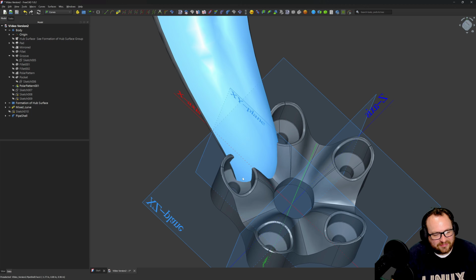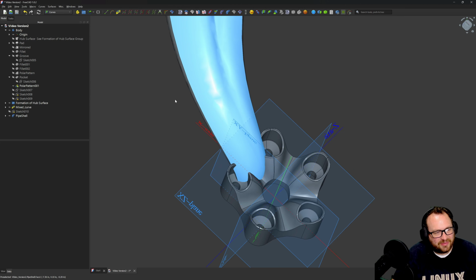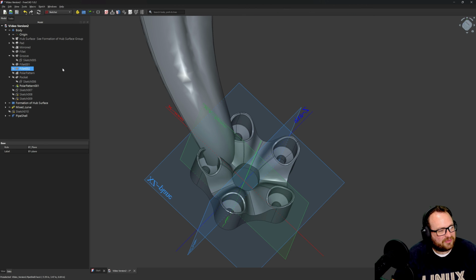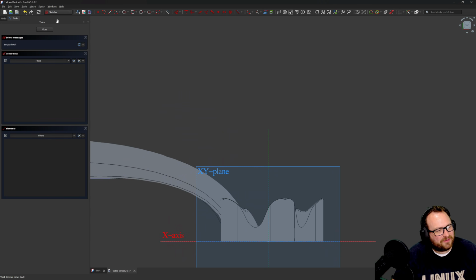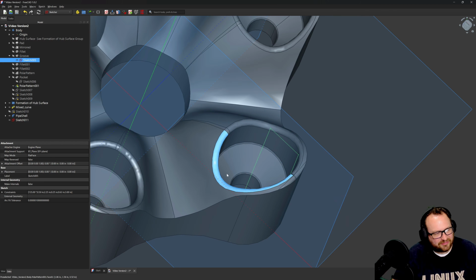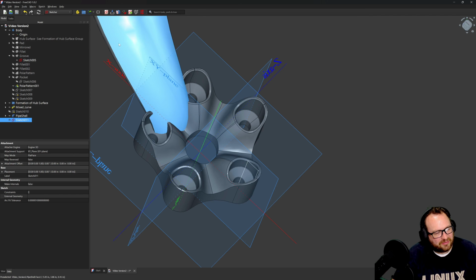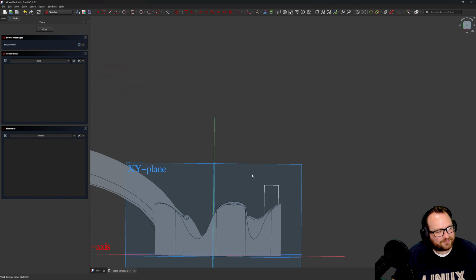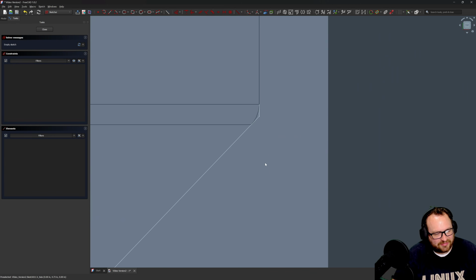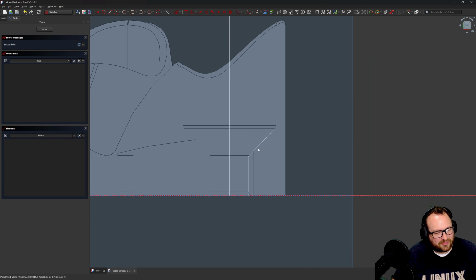But first, let's create something that will trim this spoke so we don't have to worry about it. I'm going to go with sketching on the XY plane. So again, we'll go to Sketcher, create a sketch, and we'll choose plane face. And from here, you know what, I actually need to close it because I need to go find my groove, which is right there, and show my sketch that created this originally. Now I can go to my sketch 11 and jump back in. I'll use this option to trim my sketch so I can see things. And there's my original sketch profile.